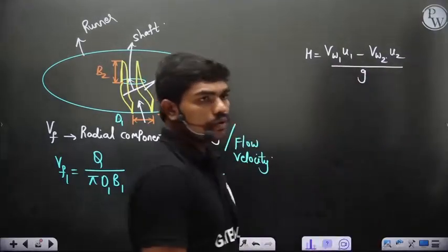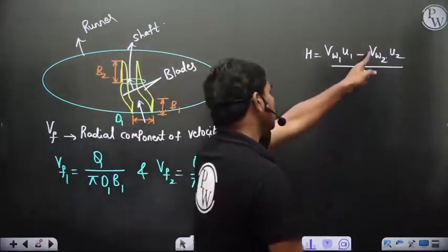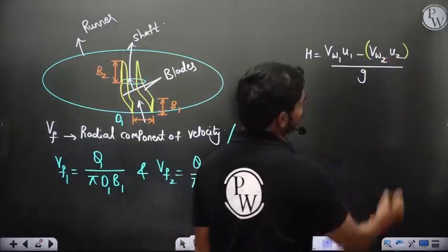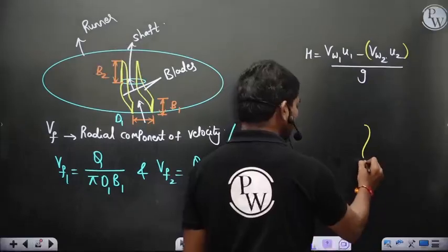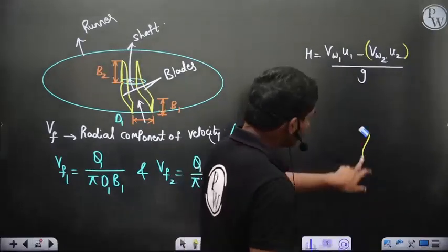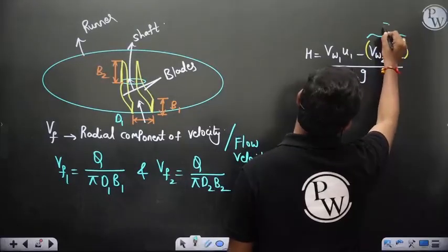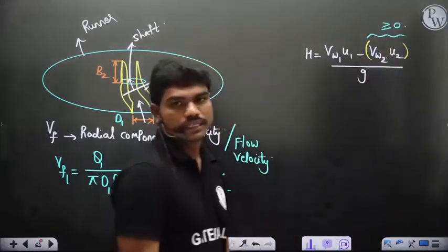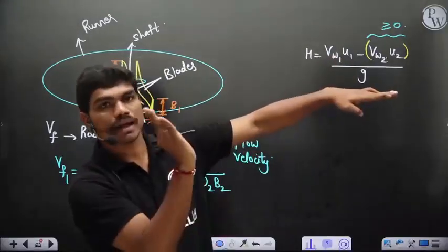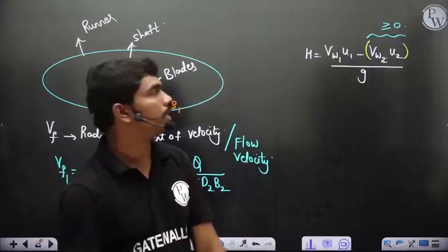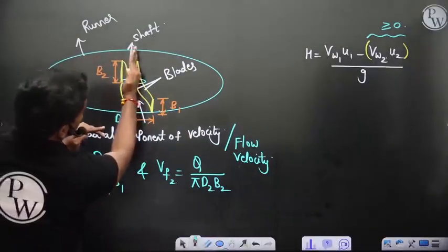Basically this has a contribution from the pressure side as well. This Vw2 term is positive obviously, if you look at the vane angle, with some inlet and outlet. This term is greater than or equal to 0 generally. In this construction of the Francis wheel, the blade cannot be bent backward, because ultimately it's like twisting the blade and breaking it. You cannot twist this portion back again.